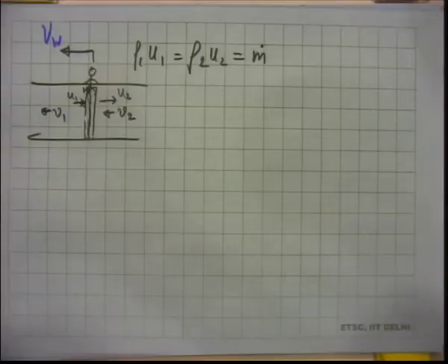Now, what's the unit of rho 1 U1? Kg per meter squared second. So kg per meter squared second, as I said, strictly should not be written as m dot, because m dot gives you the unit of kg per second. But I am not writing the double prime.